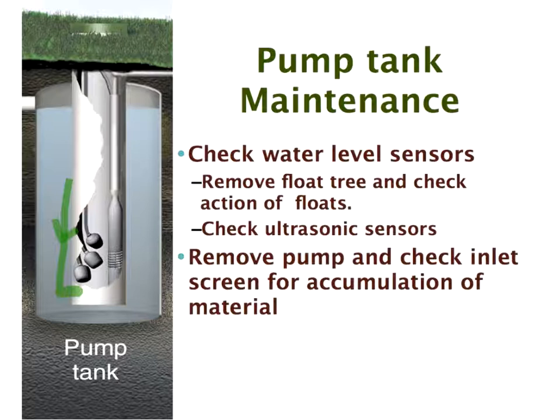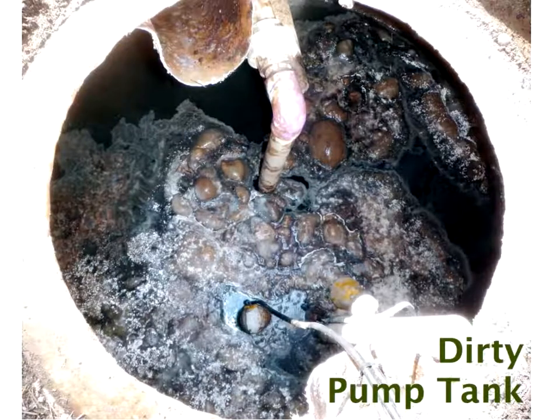Check that the inner screen on the pump is clean, because, of course, we are dealing with sewage, even if it has been through a treatment plant. And as I said earlier, it doesn't matter. There is no treatment plant, and I hope no treatment plant manufacturers get into a fight with me, but there's no treatment plant in small systems that doesn't sometimes go wrong. And there's no treatment plant even for municipal systems that doesn't sometimes go wrong, as we read in the newspapers every day.